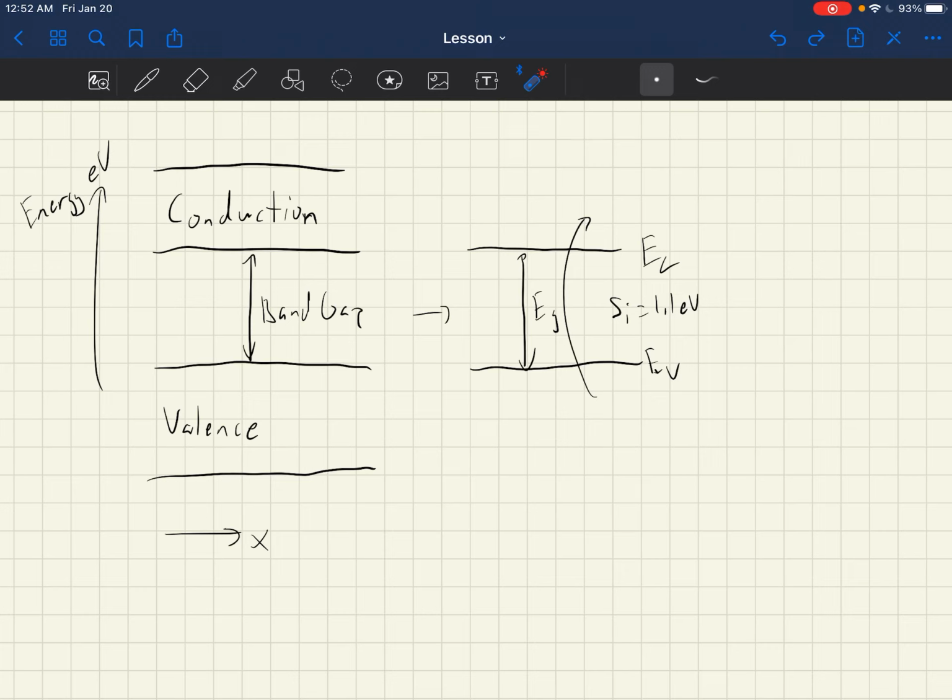The electrons or the charge carriers are filled up here, and they want to jump up to here so they can conduct electricity, or conduct a current, or a charge. What they have to do is go over this band gap. There is nothing in this gap. It's empty. So imagine jumping over a river or a little stream. There's no land in the river. It's all water. So you want to go from there and jump across. Well, to do that, you need a certain amount of force to get across it. For this case, the force is electron volts. That's the unit we're using.